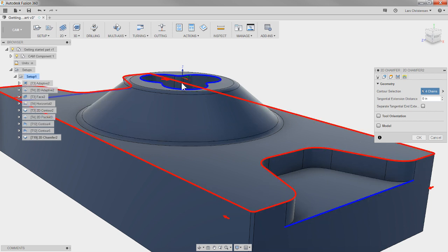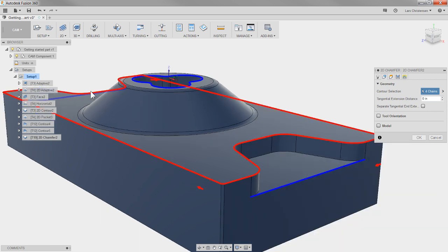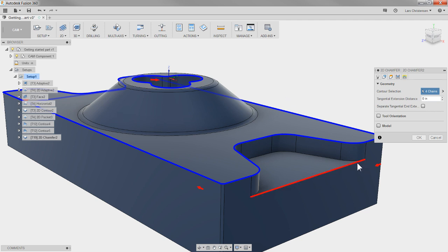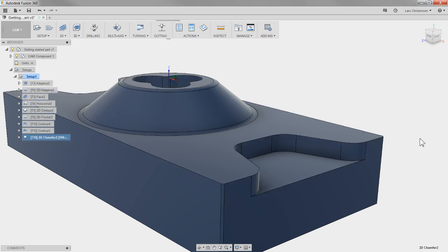And if you've ever done some regular chamfering in your machine, and I'm actually in favor of chamfering right in the machine instead of standing there with files, but if you've ever made this mistake, that's just horrible. But the cool thing about the 2D chamfer tool is that it knows how big the part is, and it knows the tool size, so it actually cuts it short.